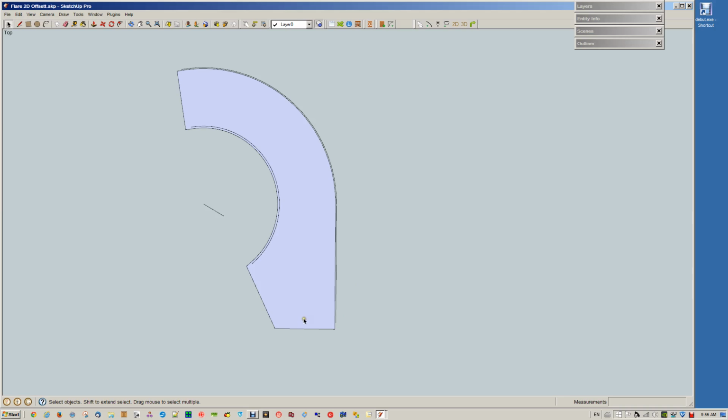Again, we do the same type of an idea. It's an offset. So we have 17 plus half the thickness of the stringer, which is 54 divided by 2 is 27. That's 44 millimeters. So the inside will be 44 and the outside will be 144. We'll go with 100 millimeters for the wall, just for easy math. So let's do it first, 144. And let's do it again. 44.